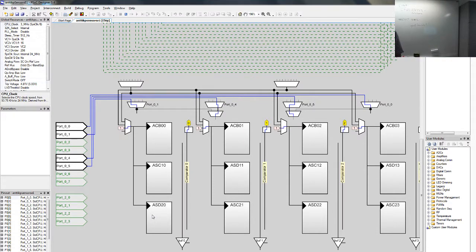Have you heard of switch capacitor technology? Okay, that's how you make a variable resistor, by using only switches and capacitors. Simple. Two switches. This is the fundamental principle. There you have a constant capacitor. Okay, this is input, that's output.